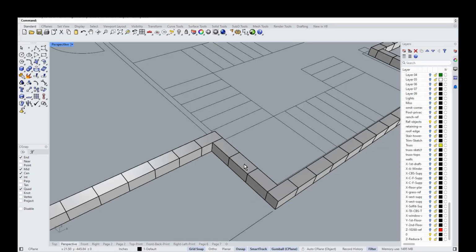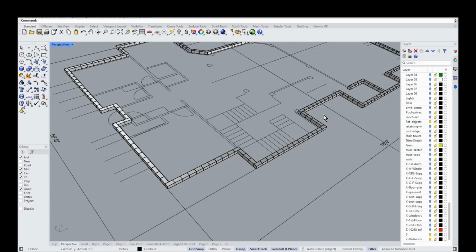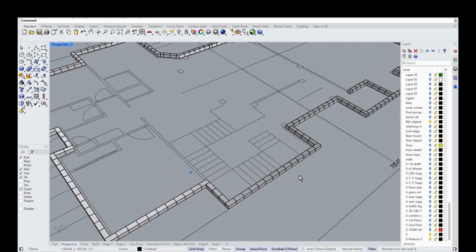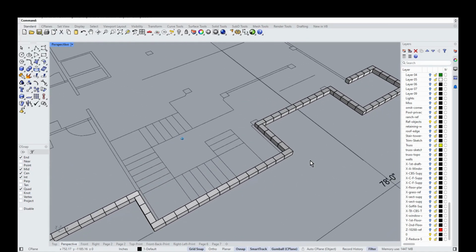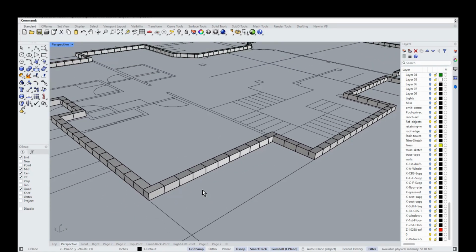But it goes to show you how you can just put a bunch of these blocks down on the flat plane axis. Normally Z's pointing up when I'm working on these architectural things, and it will let you do a layout that is honest for block course. So they should not have to cut blocks, and if they do, it'd be very minimal. So that's just showing the layout there, and it gets that all set up.